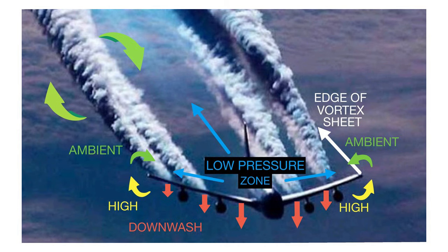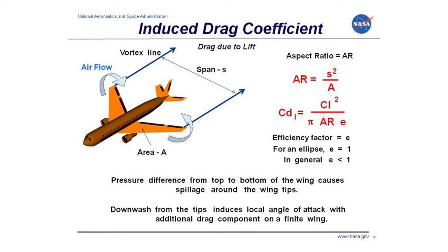So back to our big question, how can we minimize the energy lost to overcoming induced drag? Or in other words, how can we minimize the amount of energy lost to the rolling up of the wingtip vortices generated by the span-wise flows induced by producing the necessary downwash for our flight condition? It should be obvious that maximizing the aspect ratio of a wing will minimize the induced drag generated. With the higher aspect ratio wings, the lift distribution becomes more efficient across the span of the wing, and the wing generates less intense wingtip vortices because there's less span-wise flow towards the tips, leading to weaker vortices and therefore reduced downwash.